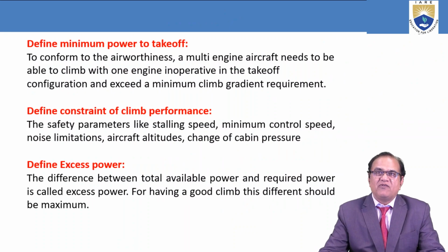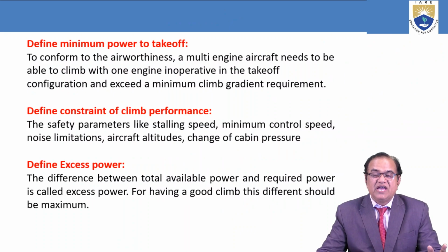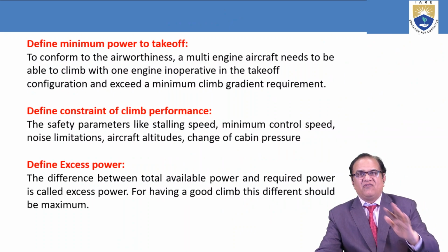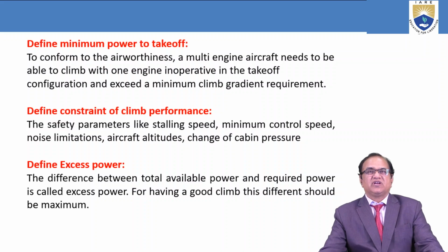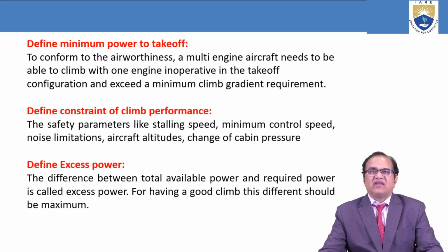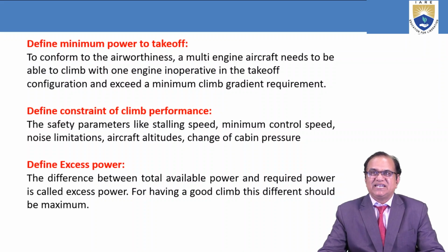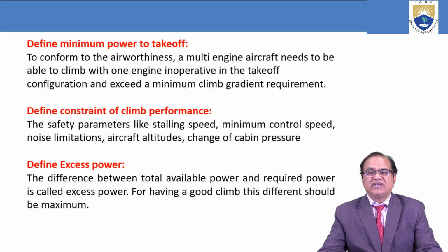Define minimum power to take off. As you know, during the takeoff, an aircraft needs some extra power. So how much power is required? A minimum power, how much is required for the takeoff of the aircraft? To conform to airworthiness, a multi-engine aircraft needs to be able to climb with one engine inoperative in the takeoff configuration and exceed a minimum climb gradient requirement.